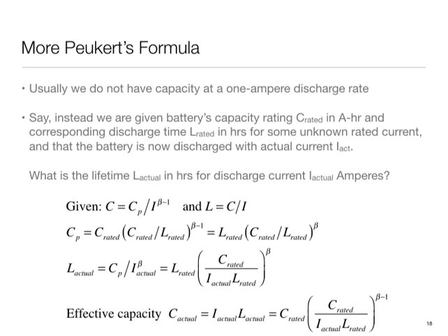That's what batteries score. Remember I described earlier that when batteries say that their capacity is so many amp hour, then the current at which that battery is rated is that number divided by 20 hours. Essentially, the battery capacity is defined for that current, which will lead to a 20-hour battery lifetime. That's the number you usually have from the data sheet of the battery. Well, you don't have a number at 1 amp.